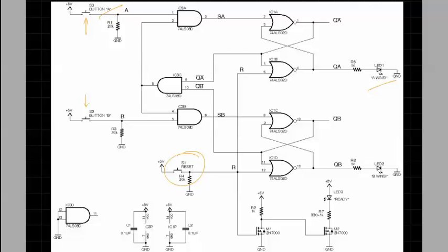Okay, so here's how it works in essence. I'm not going to explain all of it because I want to leave some of this discovery to you, but here are 2 RS flip-flops, this one is flip-flop A, and this is flip-flop B. The output of each of these drives the LED. So when Q of the respective flip-flop goes high, that respective LED will turn on.